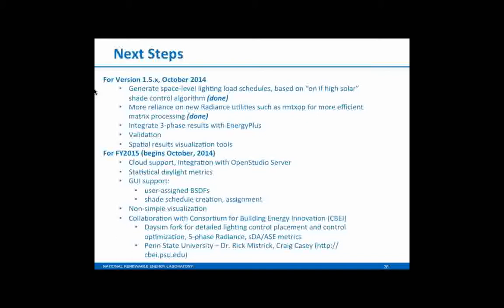And hopefully, down the road, we see a path to using OpenStudio and the SketchUp plugin or whatever to make your model and do your basic whole building simulation. But now maybe you have a couple of spaces that account for a lot of the square footage. Maybe it's a school, for example, and you've got four different classroom orientations. If you get those right for each exemplar classroom orientation, you can optimize the daylighting controls for 80% of your square footage.